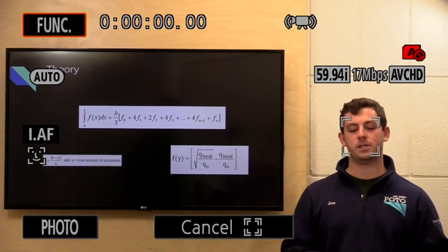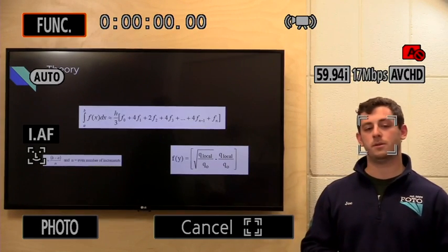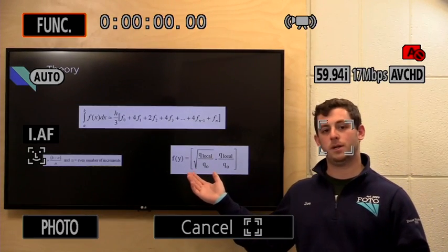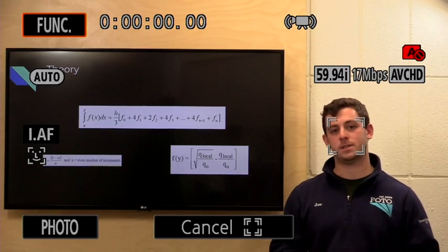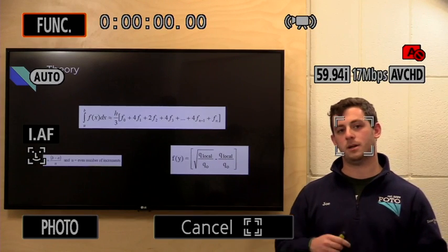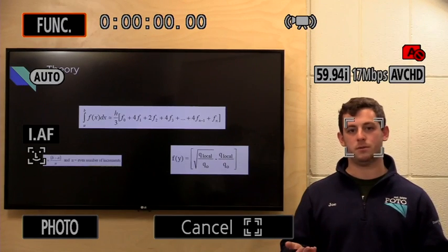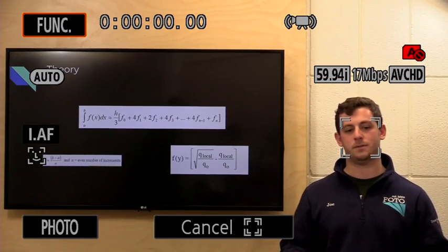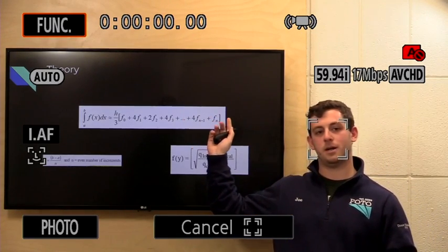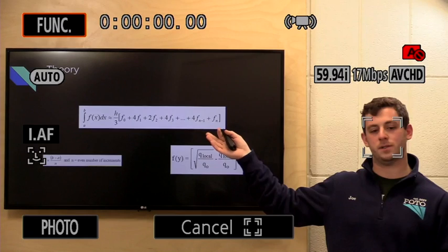Simpson's rule is an integration of the wake profile experienced behind the airfoil. So the first equation we want to look at here is the F of Y equation, which is looking at individual points in the wake of the airfoil, looking at the dynamic pressure in that local area, as opposed to the dynamic pressures at the beginnings of the wake, and seeing the difference there. And then we integrate that across over the entire surface of the airfoil, or entire core of the airfoil, for each upper and lower surface.